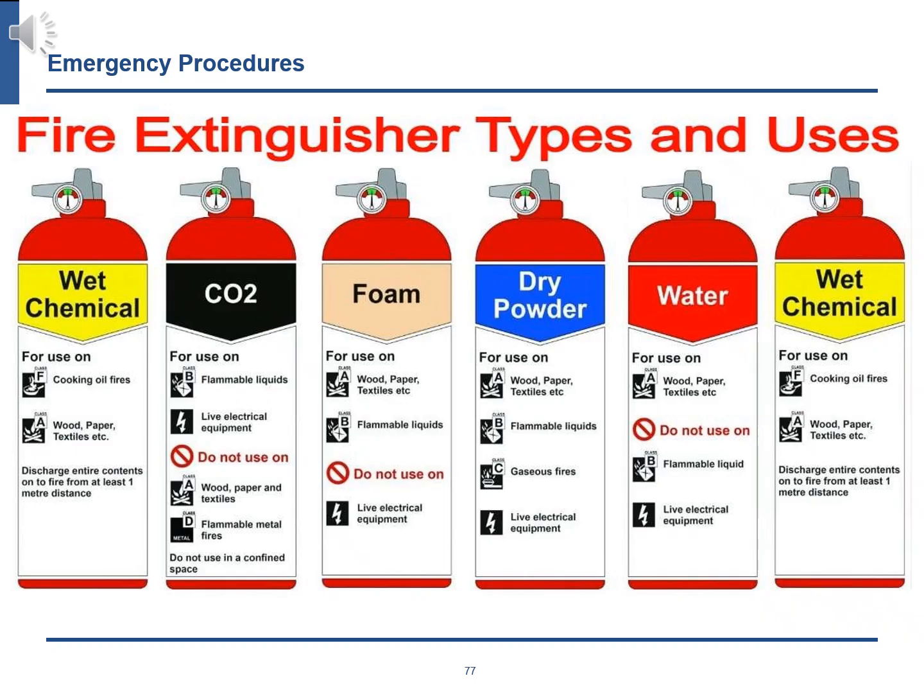Unsuitable fire extinguishers. Water-based extinguishers should never be used on electrical fires because water conducts electricity, which can lead to electric shock and potentially spread the fire. Foam extinguishers. Similar to water-based extinguishers, foam can conduct electricity and should not be used on electrical fires.